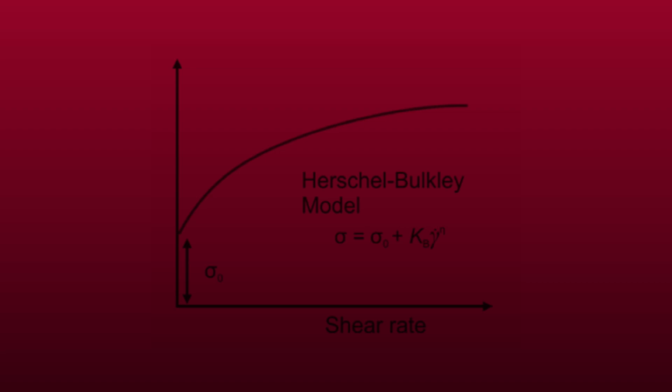The Herschel-Bulkley model combines the strengths of both the Bingham plastic and power law models. It includes a yield stress component as well as a nonlinear shear-dependent term. This makes it one of the most accurate models for describing complex drilling fluids. By accounting for both yield stress and shear thinning behavior, it provides better predictions of pressure losses and hole cleaning performance, especially in challenging well geometries.